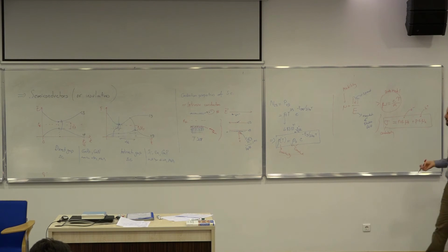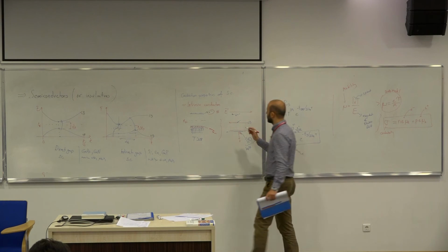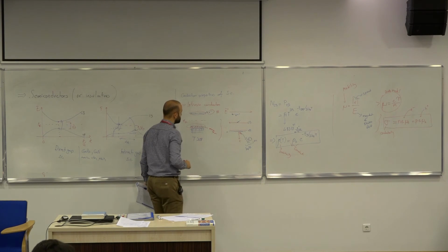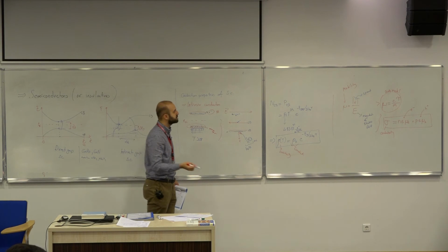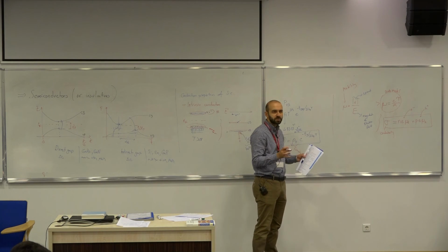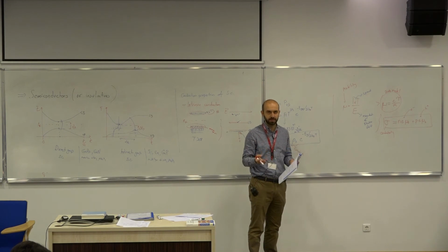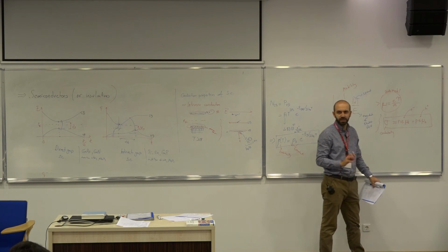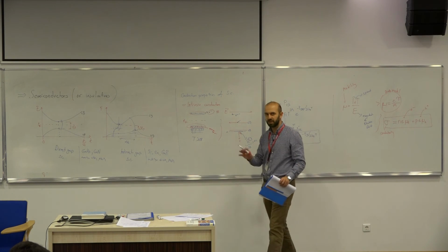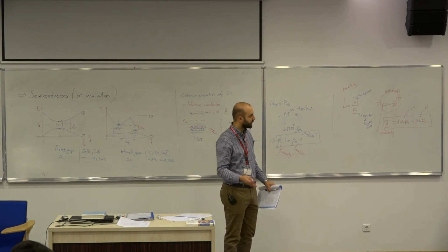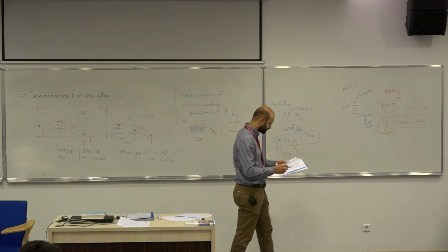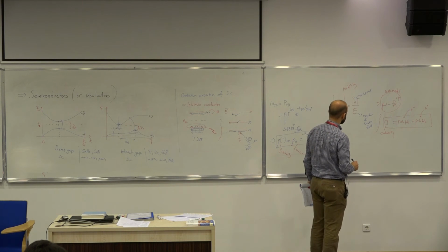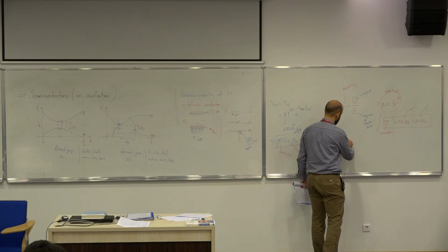So I'm assuming basically when I focus on the edge of these bands, I can approximate that these electrons sort of behave like free particles. So I go back to my Drude model to write down such an expression. And it turns out this is not a bad assumption after all, and it fits quite well with the observed values. There's one other thing that I would like to explain, which is called the effective mass.